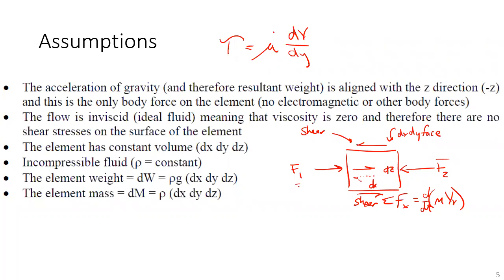So by saying we have an inviscid fluid, we're saying that the viscosity is 0. And therefore, none of the shear stresses that I just drew on all these faces exists. That makes the sum of the forces term easy. Is this realistic? Of course not. But we're walking before we're running.